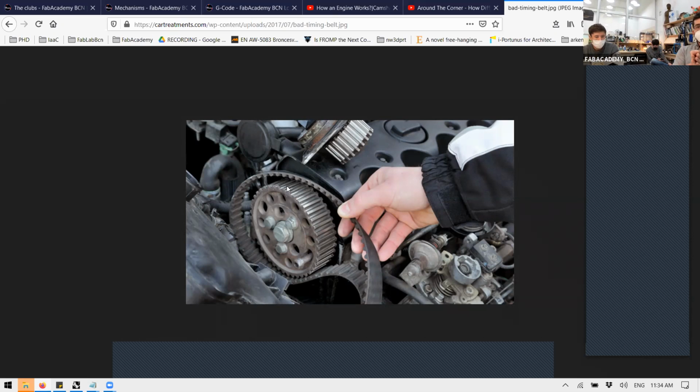First, you cannot change gears with a belt. You only can have one ratio. Even so, some bicycles only have one gear. For example, if you just have one gear, a chain mechanism is efficient up to 98, 99%. You only have 1%, 2% of power loss with a metal chain. With a belt, it's 3, 4%. It's not a lot, but it is.